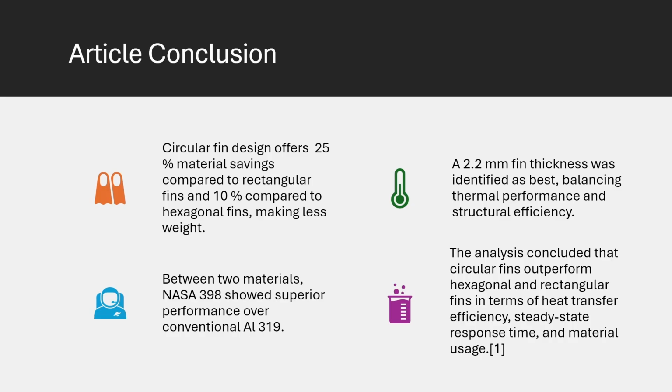If you use more thickness, it will not be that good thermally, and also the weight is increasing, which we don't need. In conclusion, circular fins outperform both hexagonal and rectangular fins in terms of steady state response time and material usage.